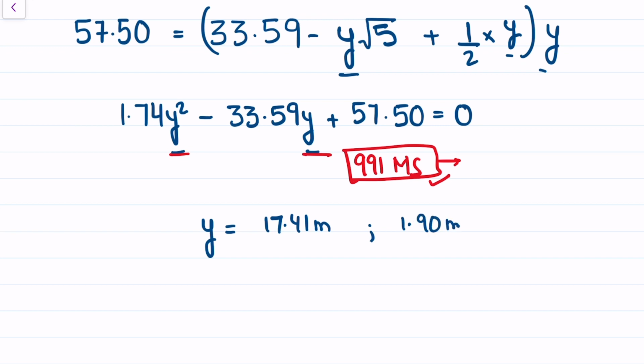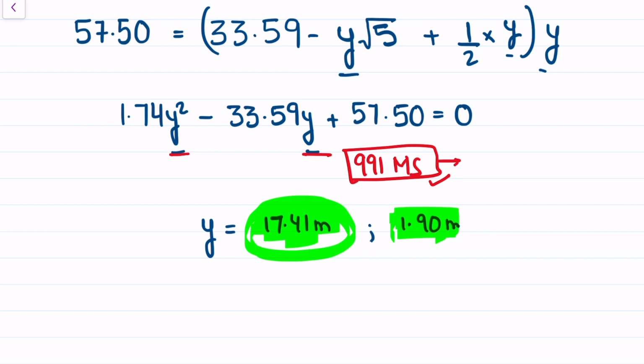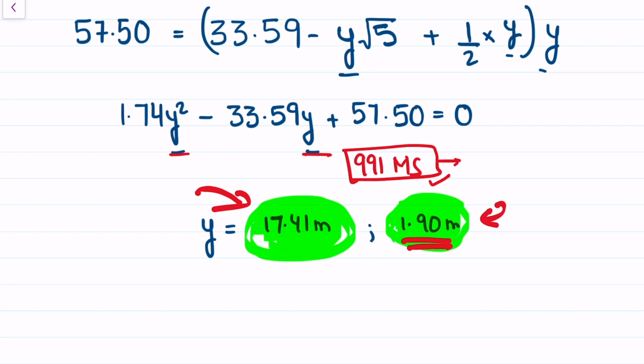Okay, so definitely which value are we going to choose? We are going to choose 1.90 meter because this is oversafe. Both depths will do the same function, correct? So why not go for a depth that is comparatively lesser than the other? If we choose the larger depth, it becomes an uneconomical approach, while this is an economical approach. That's why we are going to take 1.90 meter.